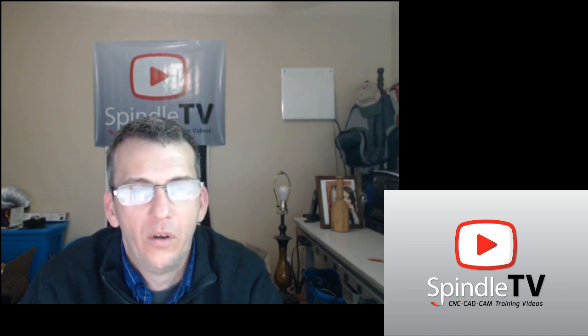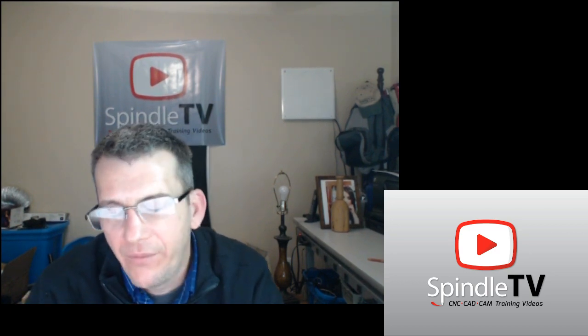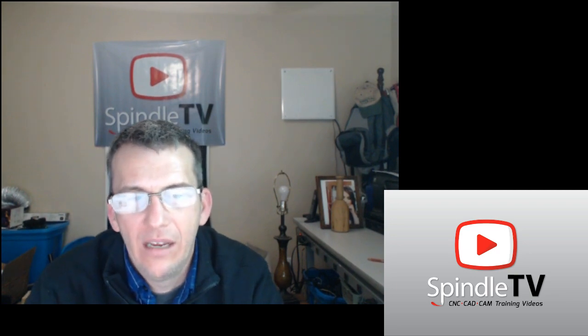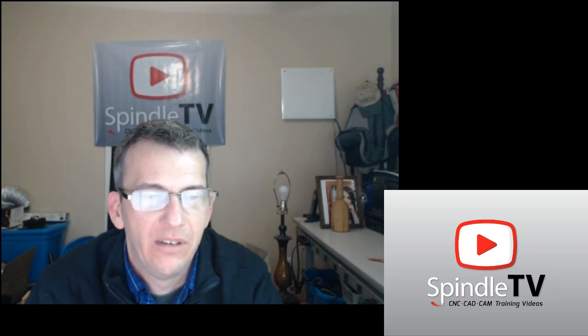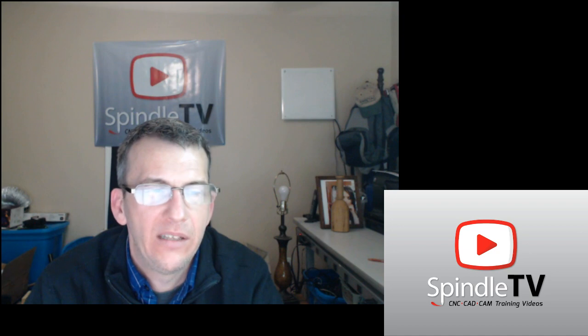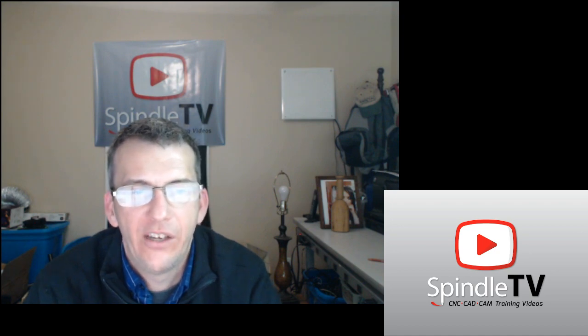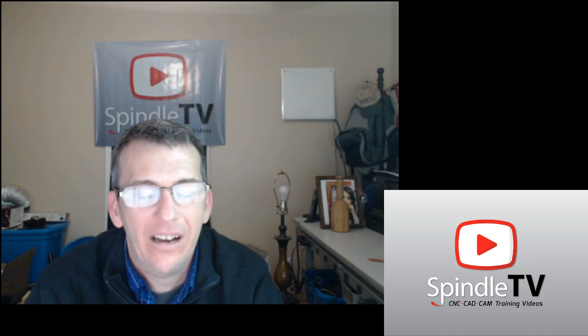For that 1/8 inch ball nose, we're probably going to be around 22,500 RPM if you do have a spindle. If you have a router and you're turning the dial on your router 1 through 6, you'd probably be about 5 on the dial. And we'd be running that 1/8 inch ball nose around 50 inches a minute, plunging around 20. But again, feed rates and plunge rates are based on you, how fast you want to run. And it's also based on the ability of your machine. And also the cut quality.